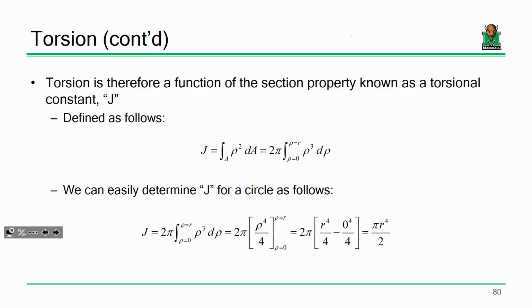A couple things though. A section modulus is actually in inches to the third. That's number one. And number two, section moduli are direct. Their direct application is in bending. In other words, if you have the bending moment on a beam and you divide that by the section modulus, you'll get the maximum bending stress. Now, it's a little more involved than that because you can have different section moduli if the shape isn't symmetric or what have you. But we're on the right path.